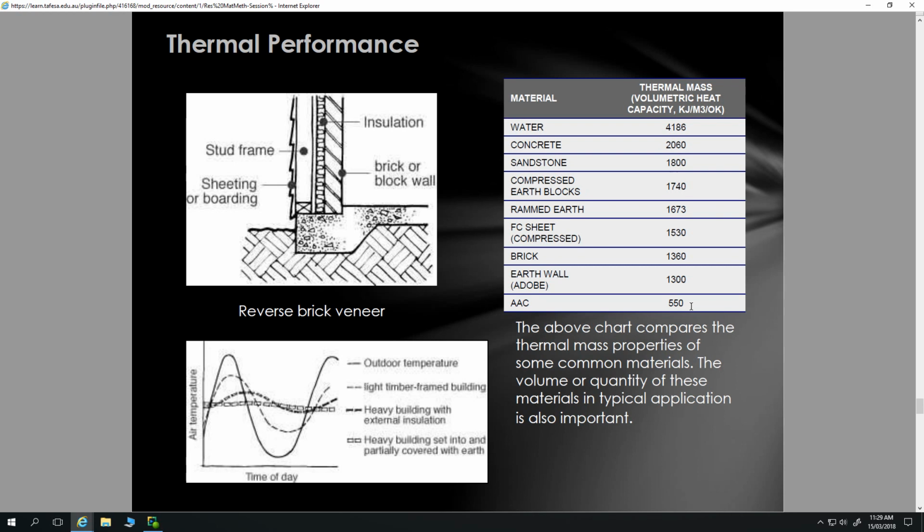As internal walls, maybe, because you don't need a lot of insulation inside a house. But if you start having walls this thick inside your house, you lose a lot of floor area. So per footprint of your building, maybe that's a poor use of straw bale. As I said, typically thermal mass can be an issue if used incorrectly.